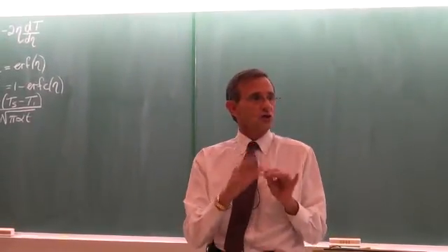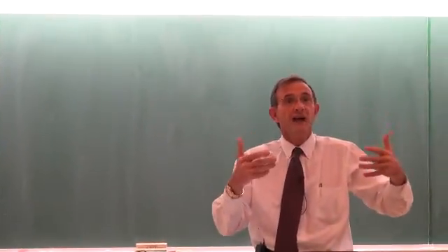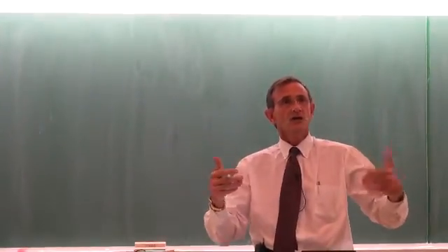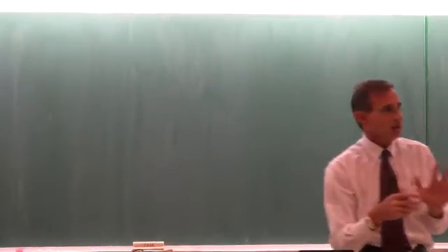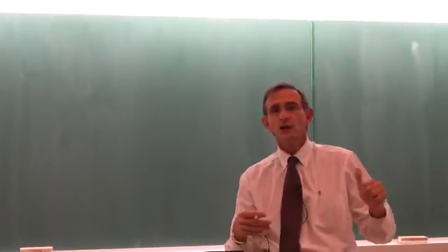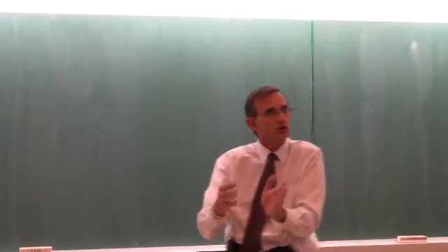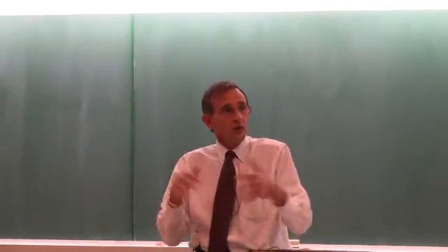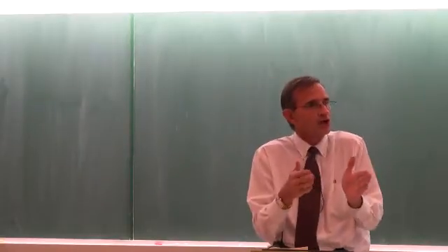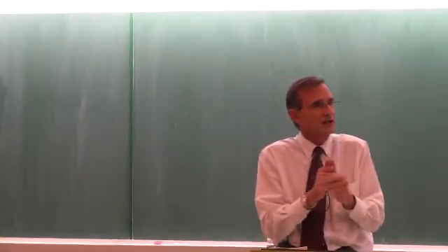Okay, now for that first term approach, you need roots which are eigenvalues of complicated equations. You can solve it numerically or you can get it from tables. The tables in the textbook are only for n equal 1, so only for the first set and not for n equal 2, 3, etc. Right. And with that, we can now solve the temperature inside plane walls, cylinders, and spheres.